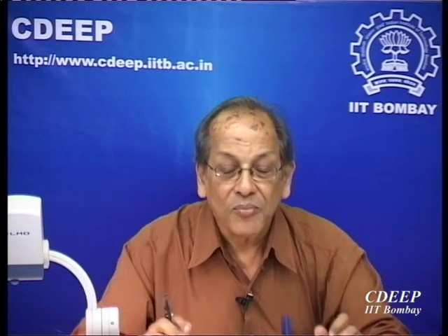That is what we have taken here. So you should know, yes, it produces tension, increases the length. So it tries to increase the length of the member, so it is a positive axial force. Positive shear force is like this. The action is like this. Positive bending moment, it is this. So be clear about why it should be positive.